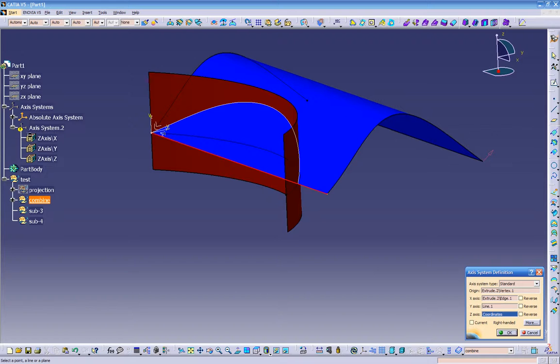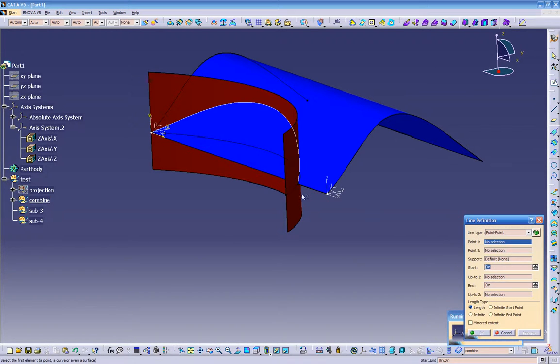The reason we didn't see the line right now is because it didn't like something about it. So we can put no selection, and you can create your line. The reason we get that little error over here is because when I click on this point, it is the point of the axis. We don't want to use this axis as a point.